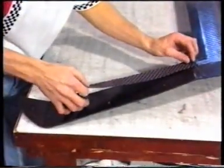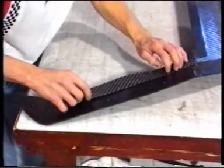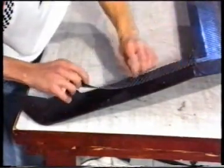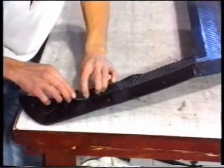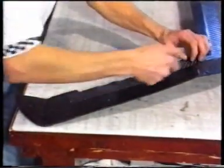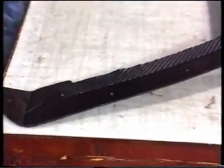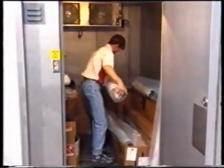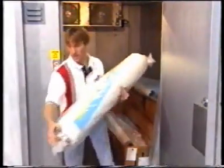Layup can also be performed using prepreg material. Use of prepreg eliminates separate handling of the reinforcement and resin. Prepreg reduces resin consumption and can improve part quality by providing more consistent control of reinforcement and resin contents. However, prepreg must be kept in refrigerated storage until use time to prevent pre-curing.